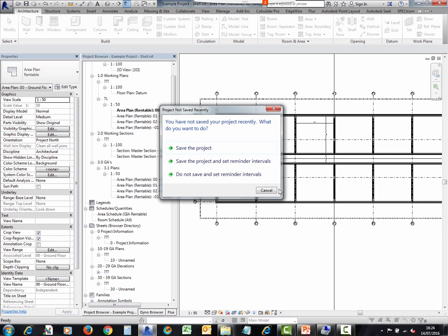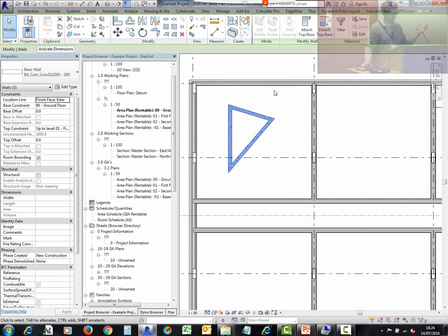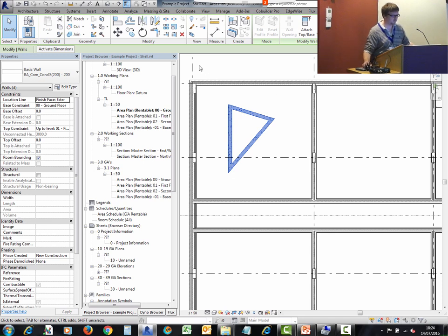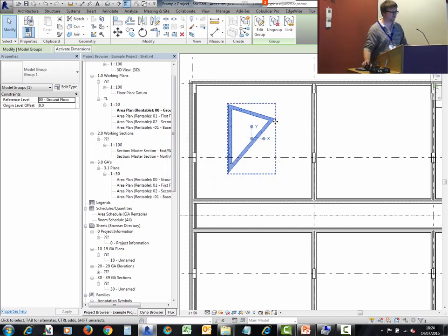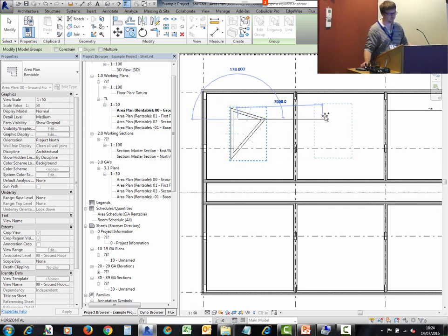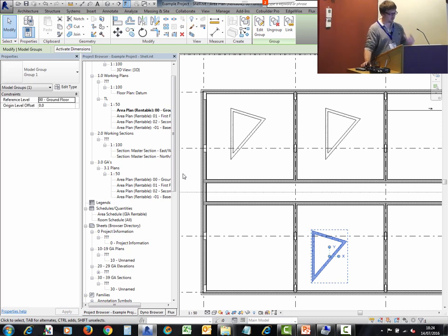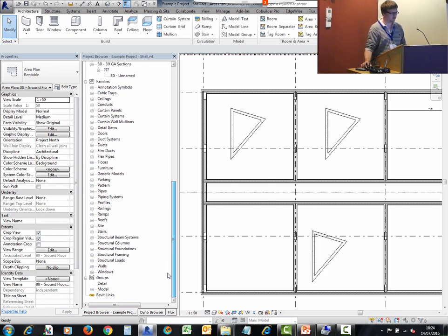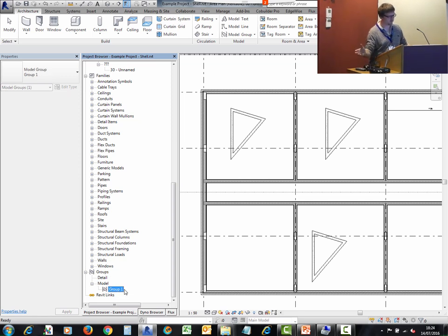As a very quick example, I'm sure everyone here would know that, just like in pretty much every program you ever use in Windows, Photoshop and so on, you can group things together. So I've just created a group there, dead quick, easy, and I can then copy that group and create further instances of it like that. Or when you create a group, you'll find down the bottom of your project browser, groups show up under the heading groups, and that's group 1, that's one I've just created.